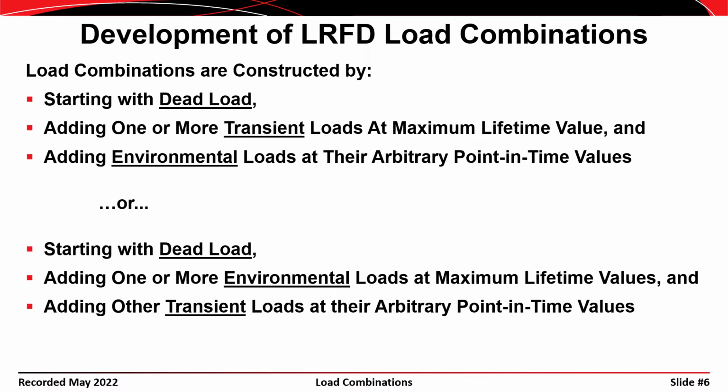So the idea here is, dead load is a permanent load. It's always going to be there. You have live load, which is a transient load, and let's consider snow as the environmental load. It's rational to design for a rather large live load with an average snowfall, or it's rational to design for a rather large snowfall with an average live load.